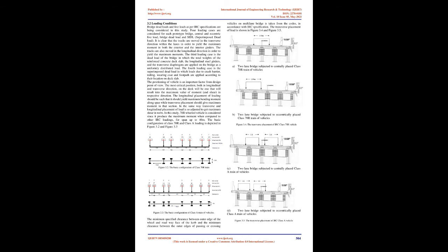26. Gholam Reza Nouri and Zahed Ahmadi, 2012. The design of skewed bridges is becoming more customary in the engineering community. In this paper, the effect of the skew angle on continuous composite girder bridges is presented using three-dimensional finite element analysis. 72 models of two-span bridges with various span ratios, n = 1, 1.55, and 1.82, skew angles, 0 to 60 degrees, and various arrangements of intermediate transverse diaphragms are analyzed.